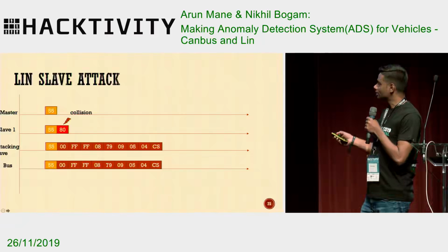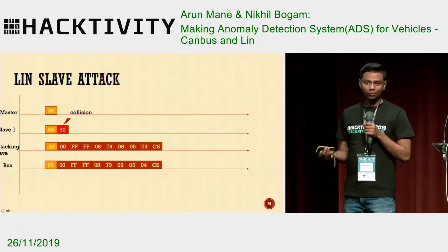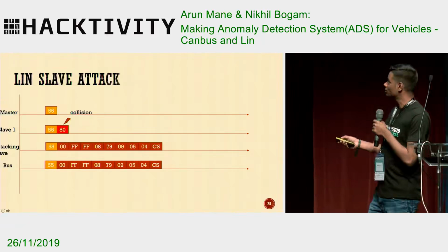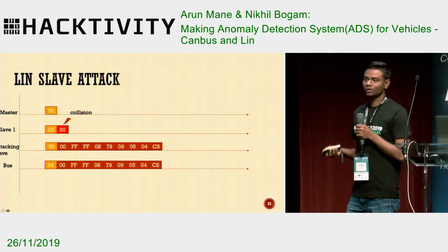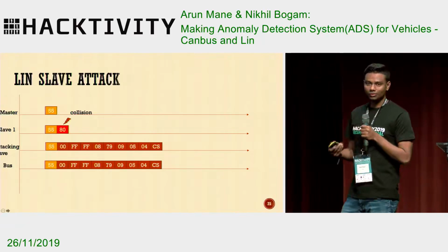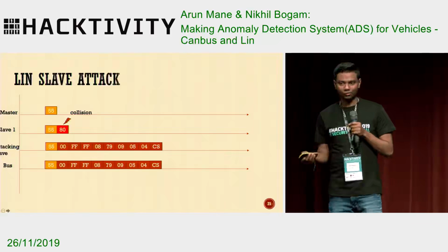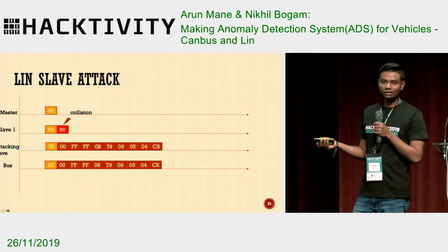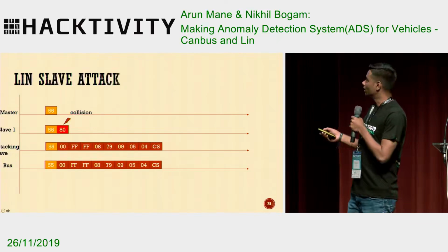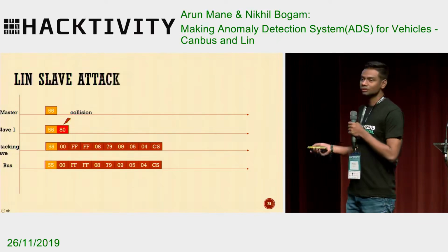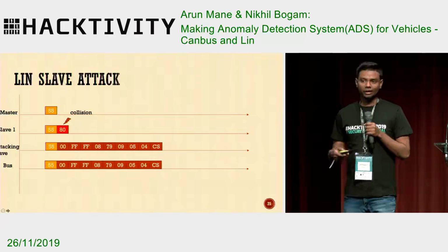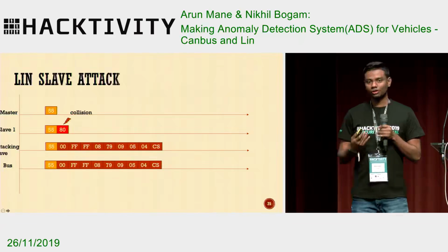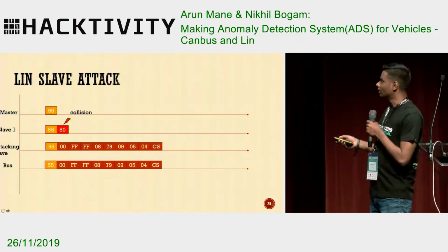On the bus it is like no fault, a normal message has been seen by the other slaves. So if slave 1 is trying to send information to slave 3 or 4, for the first byte the attacker cannot do anything, but the other bytes of information he can manipulate, and a change in functionality can occur in the other slaves.